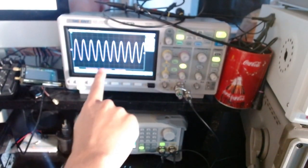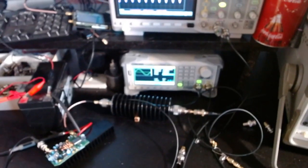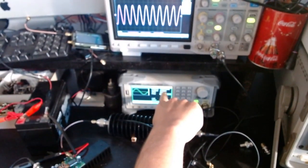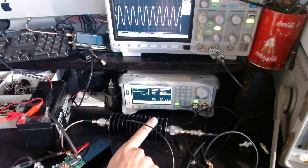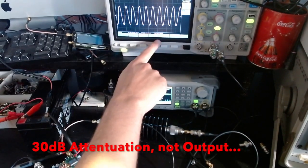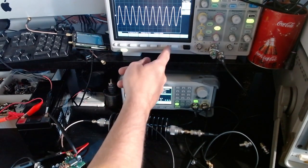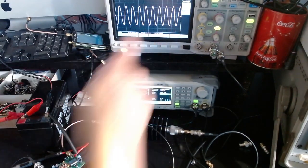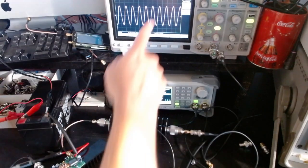Originally the amplifier was amplifying 26 dB, so 4 plus 26 is 30, and since I have a 30 dB output, in my previous video I showed that I was getting something around 0 dB in the oscilloscope, right? For an input, 26 in amplification, so 30 minus 30 equals 0.